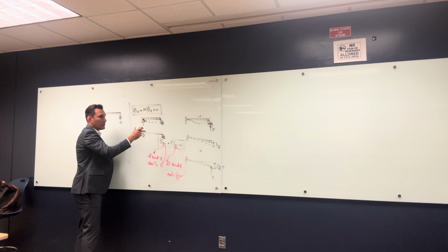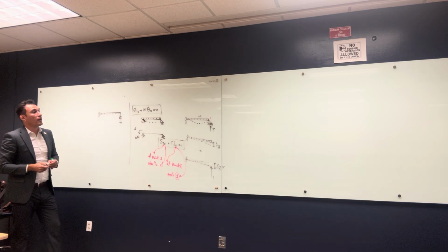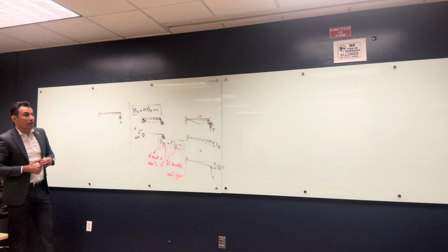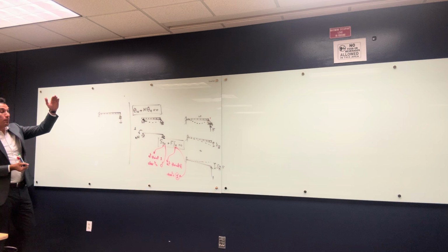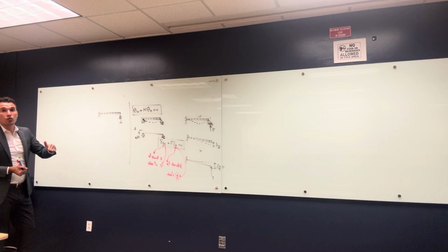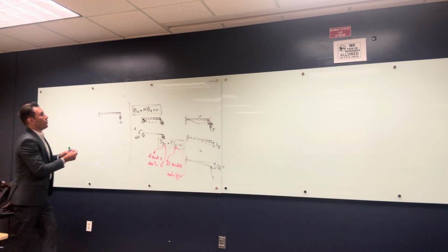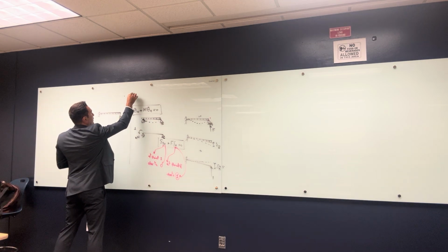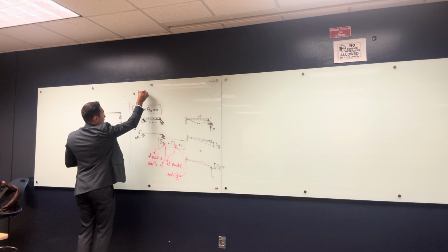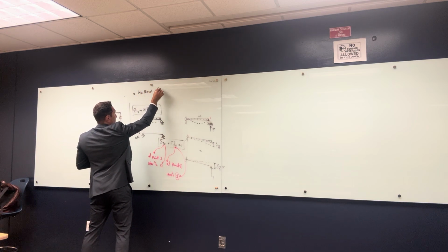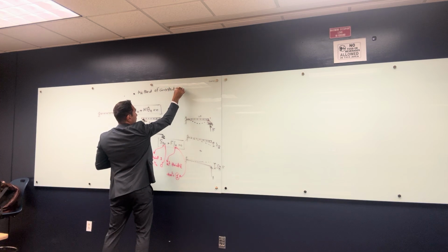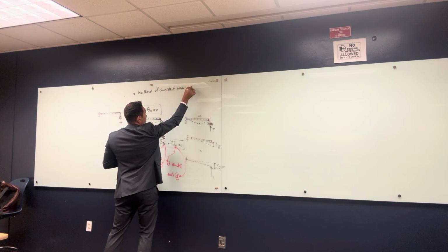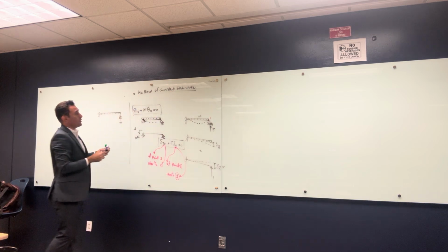I draw the bending moment here, and I draw the bending moment here, and I use the concept of the virtual work to do it. We are gonna have some examples so that we can know how to do it, and I'm gonna put the steps how to solve the flexibility method. This we call it like method of consistent redundant. How to solve using this method.